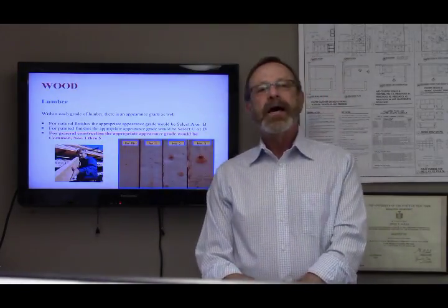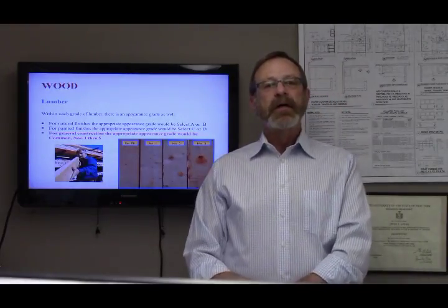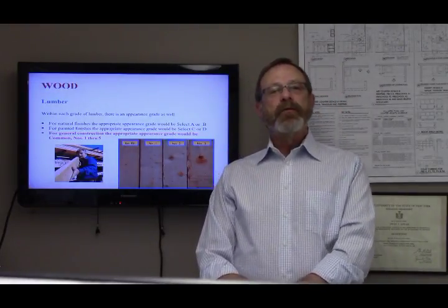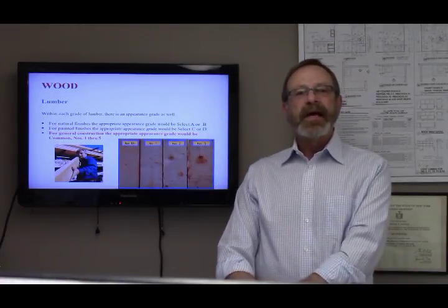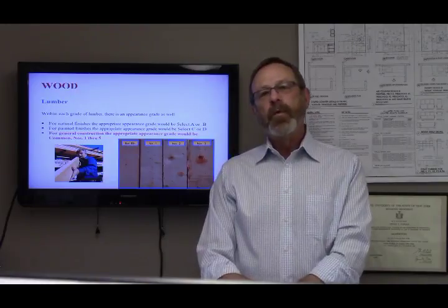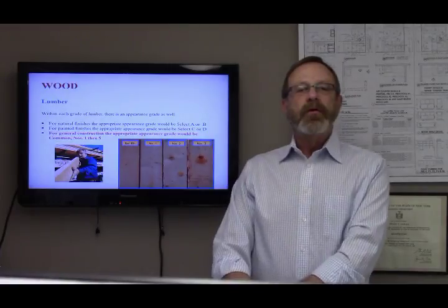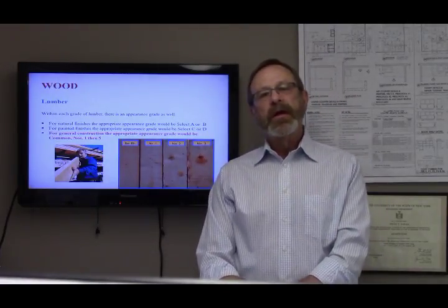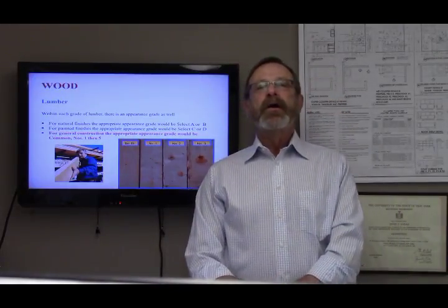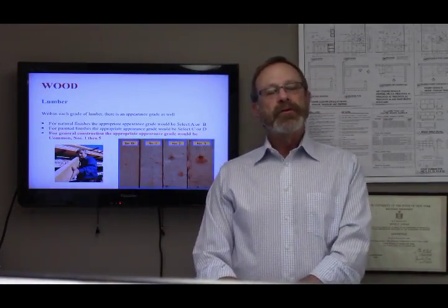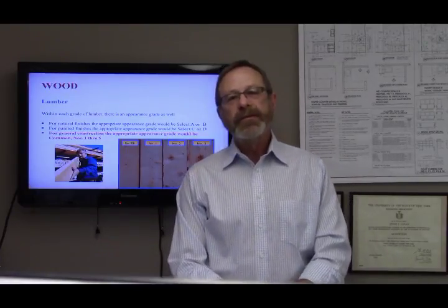So C1, common, best material for high quality pine with a knotty look. Knots will be tight, meaning they won't fall out and are generally small. 2, common, tight knots but larger than found in 1, common, often used for paneling and shelving, very suitable for general woodworking projects. And 3, common, knots larger than in 2, common, also used for paneling and shelving, but especially well suited for fences, boxes, and crates.